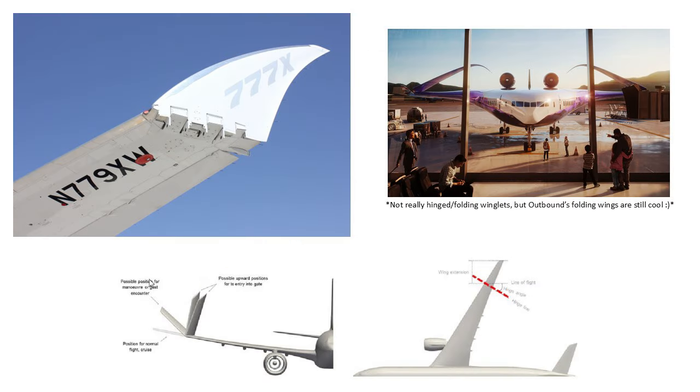All of this is super good to know for conventional aircraft, but you guys know me, big flying wing guy. So are any of these any use on flying wings? We've learned that flying wings utilize the bell-shaped lift distributions and kick the wingtip vortex inboard of the wingtip, and therefore generate upwash near the wingtips. So would a winglet even be effective?